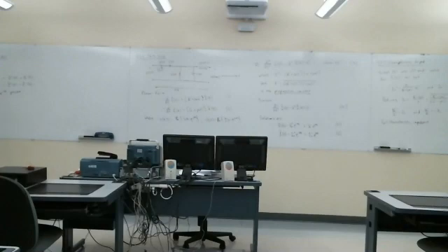You just substitute x for z in these equations, or y for z. We're still dealing with propagation down a line, in one dimension, not general three-dimensional propagation, which we'll deal with when we run into propagation in free space. We said that these are complex numbers, so I'm going to write it in exponential form with a magnitude and phase.